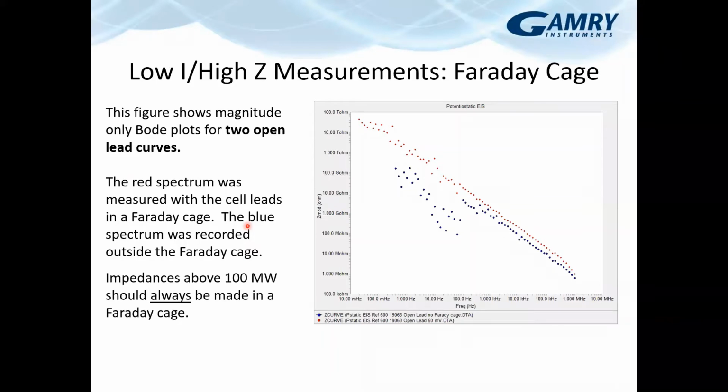And you can see two different components. First, we've gotten some more capacitance here because that Faraday cage, the way that it was set up, was actually helping to block that out. And now we've added a little bit of capacitance back in. Second, and more dramatically, is a huge shift and a big increase in the noise when we get down into the lower frequency, higher impedance measurements. All of these values are just not nearly as good, and there's a lot more noise here. That's all coming from the ambient environment. A Faraday cage blocks all of those out.